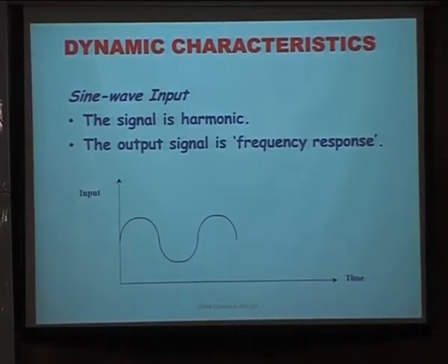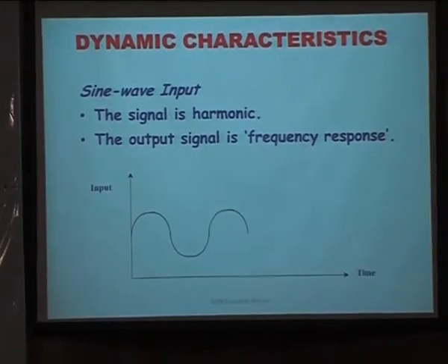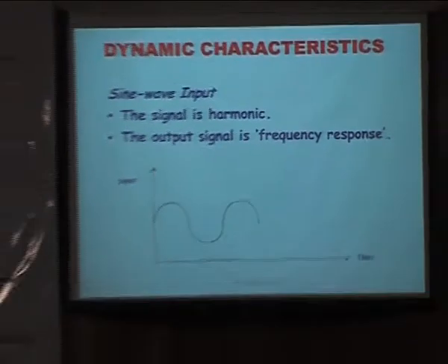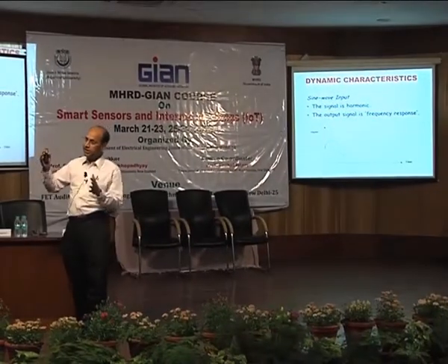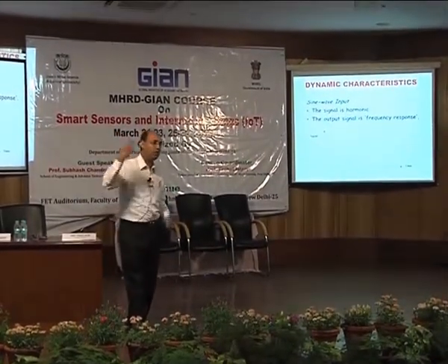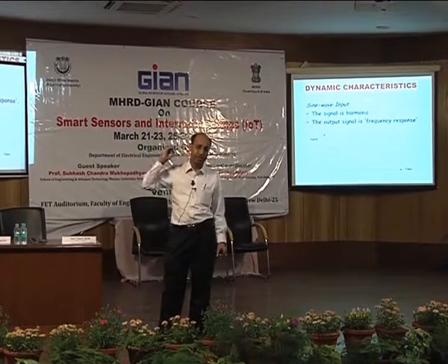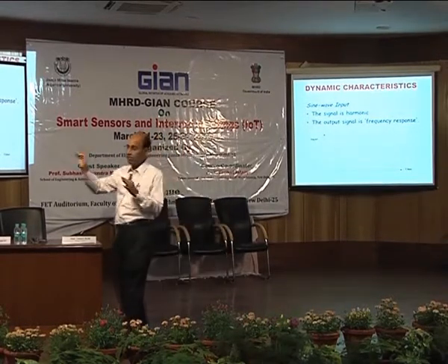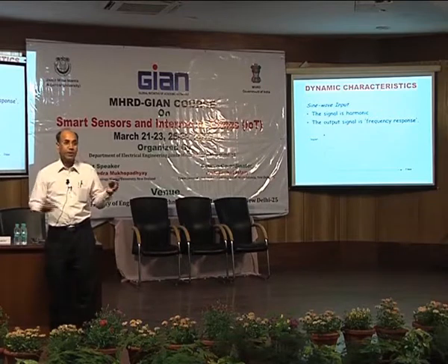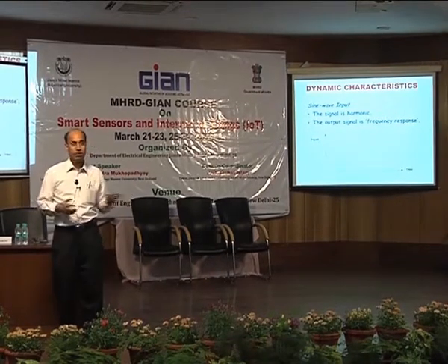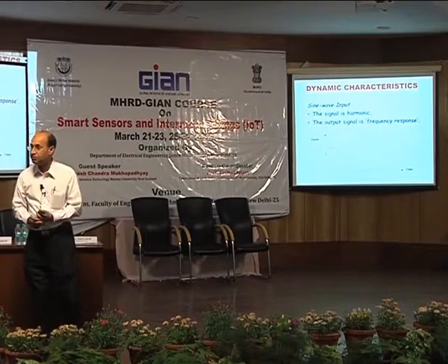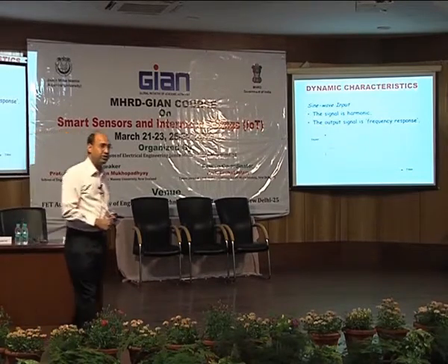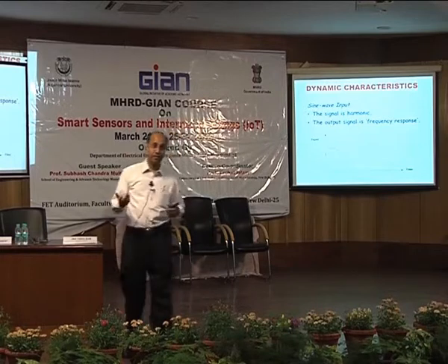Actually, the sine wave input is more to study whether the system is linear. If the system is linear, you will find that the output will also be a sine wave at the same frequency, only with a phase shift. But if the system is nonlinear, you don't know what you are going to get. Then you have to bring Fourier from his grave to analyze what components you have.